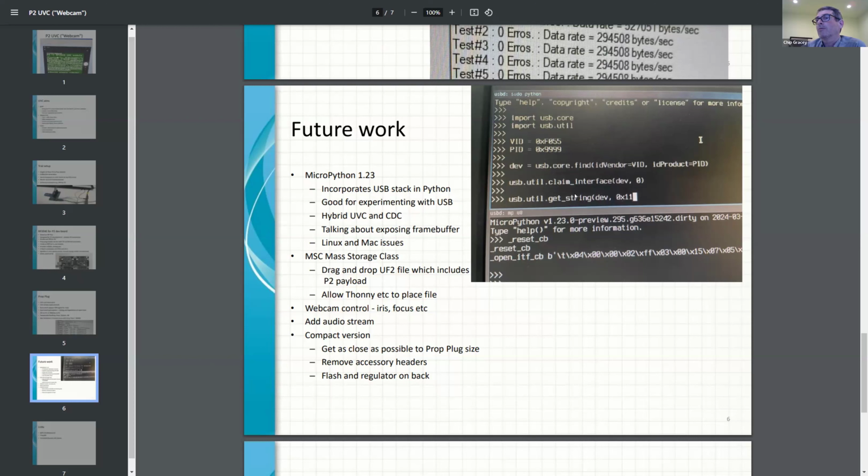But for lower rate things like HID devices, you could use one cog to handle a couple of those links, because you're never saturating the data time. Yeah, remember that from a couple months ago where I had like 7 at once? Oh, you did? Yeah. It was very funny. With HID stuff, the data payloads are small, so the conversations are very short. So you could multiplex one cog and handle a bunch of those kind of ports.